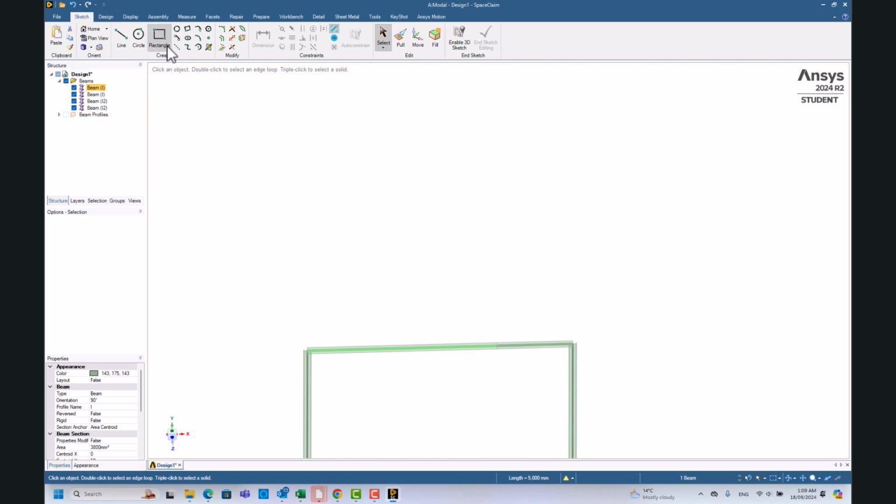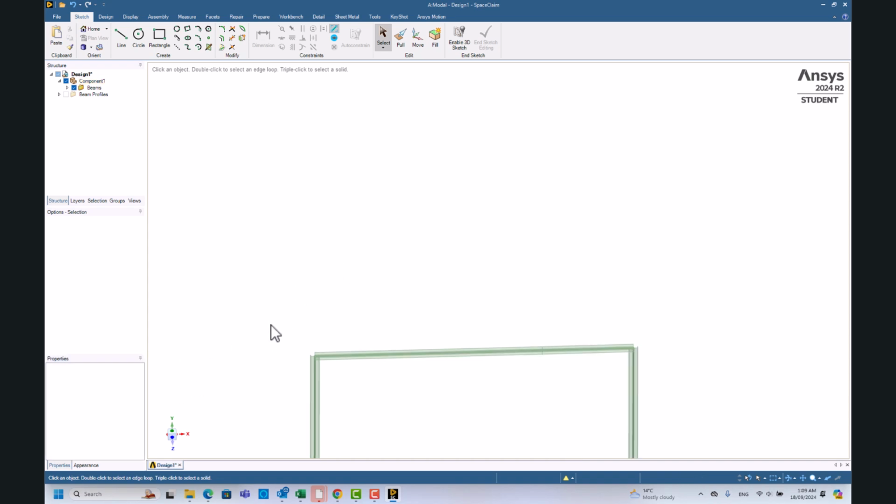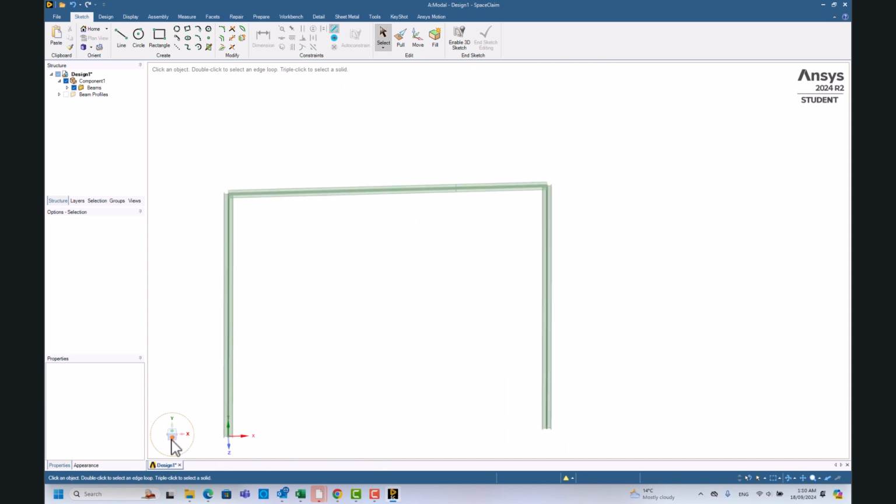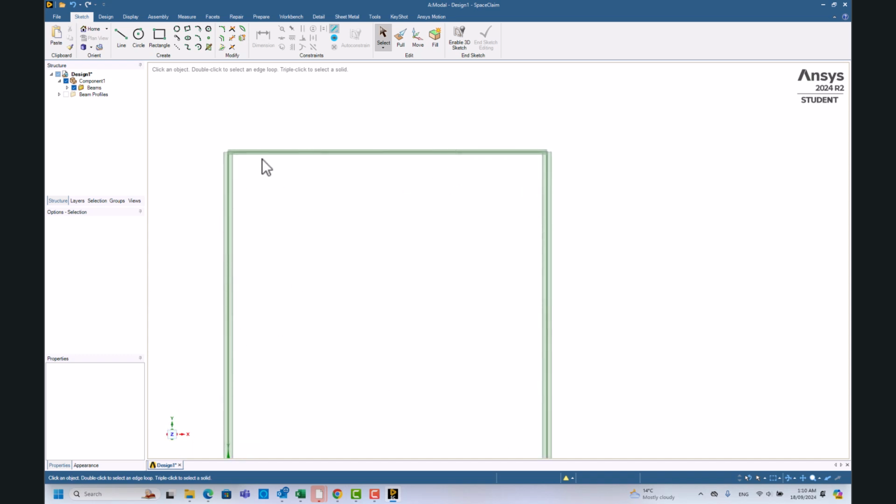The next step is to link those beams, because at the moment those beams are independent, they're just moving by their own. So you just have to join them together. So the way is to select all of the beams and move to a new component. So now all the beams belong to one component, and so you have to set the share topology into share mode. So that way we'll get a nice beam model being set, and that's done for the geometry.